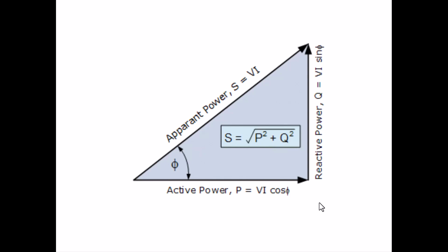Real power is the part that performs the actual work. For example, heat, light, motion. Reactive power does not do work but still causes current to flow. The total current that flows through cables and equipment is determined by the apparent power. So even if real power is less, the current is based on the apparent power and all equipment must be sized for that current to avoid overheating or voltage drops.